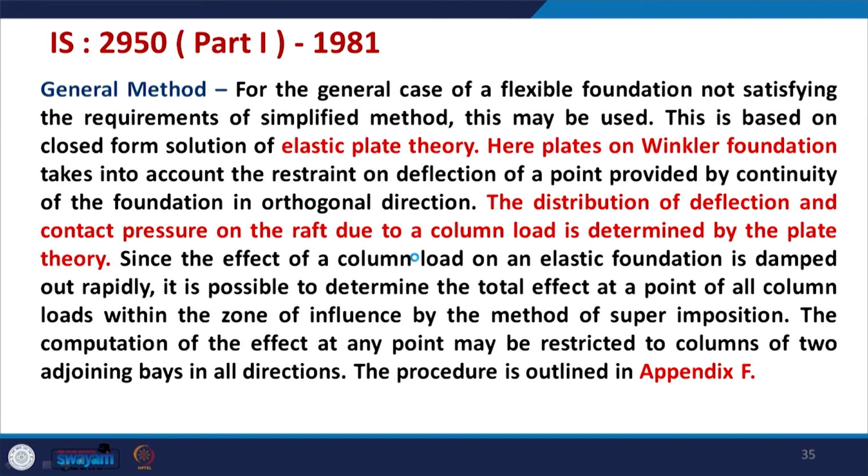Okay. So, you have elastic plate theory, and here plates on Winkler foundation take into account the restraint on deflection of a point provided by continuity of the foundation in orthogonal direction. So, basically if you recall, in the simplified method we use elastic springs, but here we do not have springs, rather plates are used on Winkler foundation. So, the foundation will be treated as a Winkler foundation and the plates, and this takes into account the restraint on deflection provided by the continuity of the foundation in orthogonal direction.